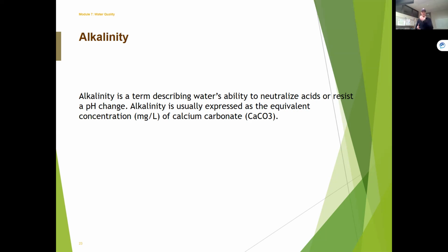Alkalinity is also really important in the coagulation process. We know that coagulation uses alkalinity in the water. So as we put more coagulant in the water, it takes alkalinity out. And if we take alkalinity out, it makes the water less stable. So it's a balance. We want to keep stability in that water, because that stability, that calcium carbonate or CaCO3, will keep the pipes safe.